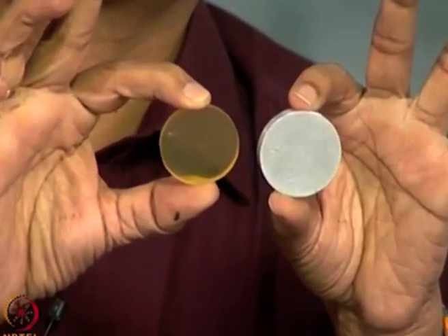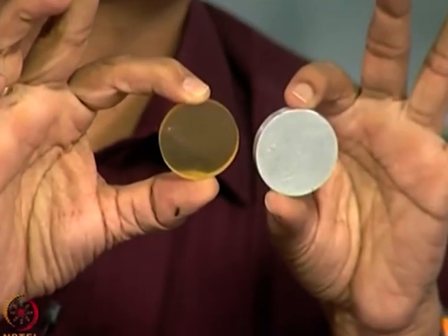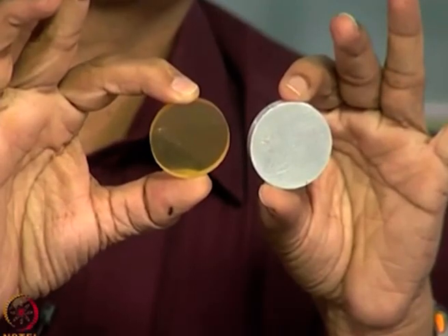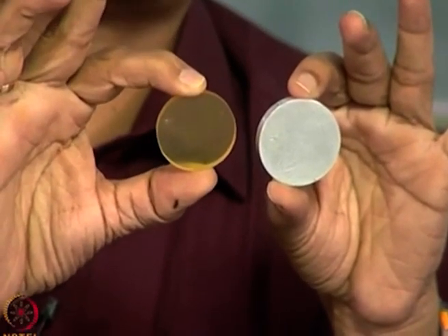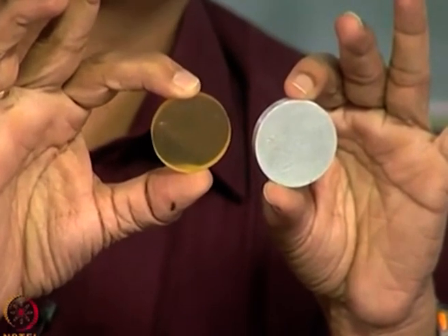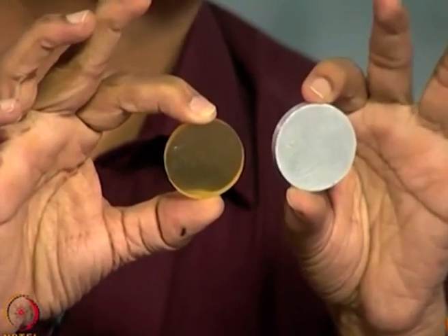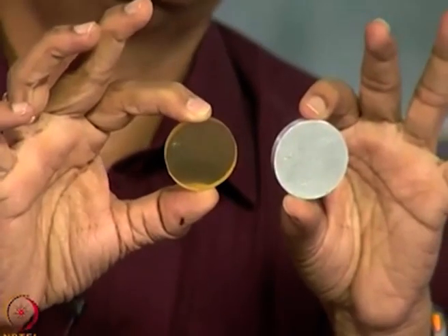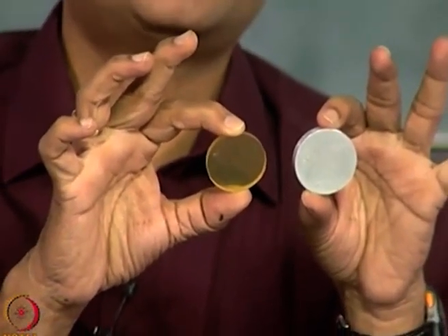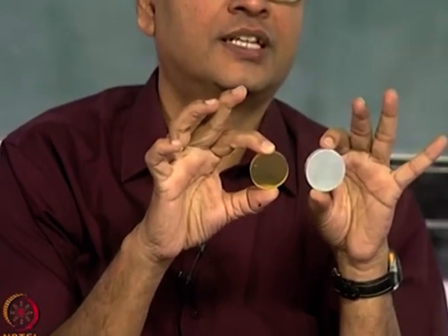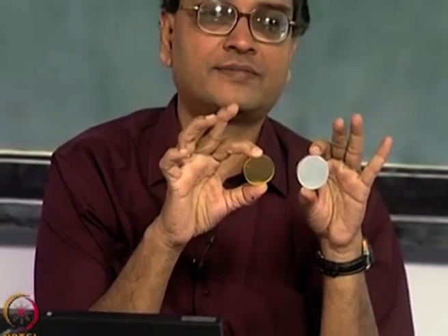I said what is the nature of the stresses developed, because polyurethane is a plastic which has a low Young's modulus, you can visually see the deformation. Aluminum is so strong, it has about 70 GPa, and this is about 0.3 GPa, it is a very small value. So, the deformation is definitely different, there is no two opinion about that.